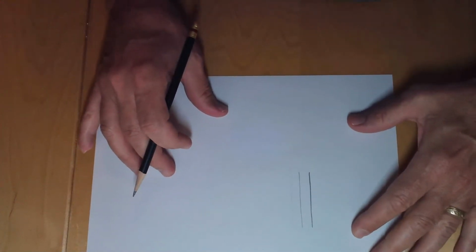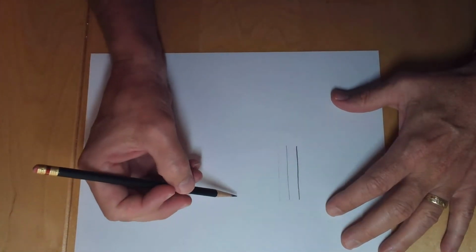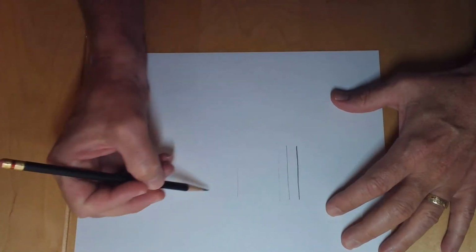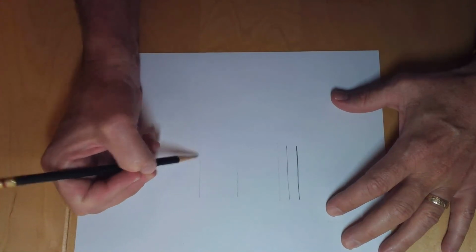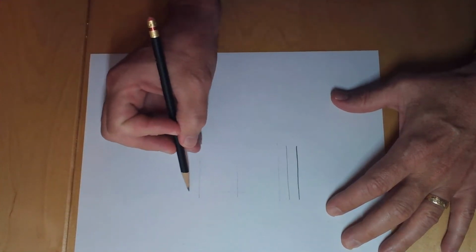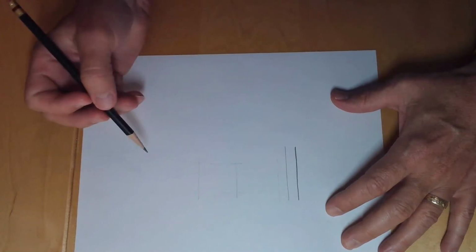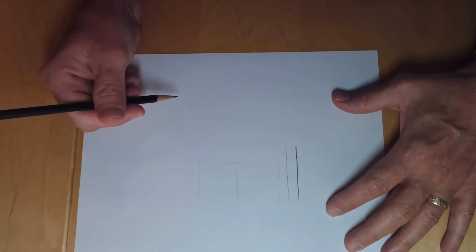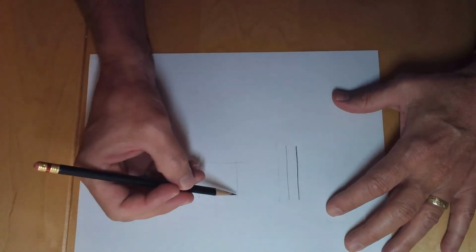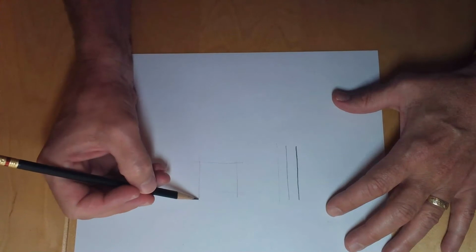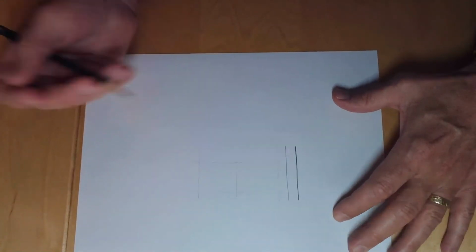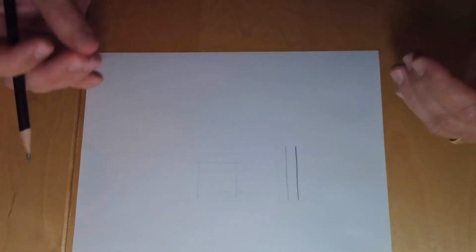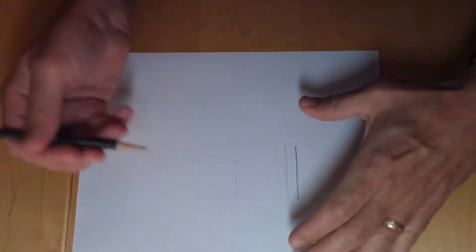So if I wanted to sketch let's say a square in here, the first thing I'm going to do is lay out the square. So this is going to be laid out with construction weight line. Now you can barely see that there. I can barely see that there. Notice that I wasn't concerned with where the lines stop and start because this is construction weight. We're just laying things out. Now we want to go over it with the visible edges, with the dark, thick line.